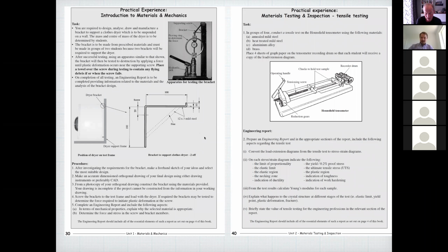It would hold together, and then I'd make sure that every student would go up there and with his fingernail feel the crack on the outside, and then I'd get them to try and feel if there's a crack on the inside. And there wouldn't be a crack on the inside because the PVB polymer between the two layers of glass has held it together. And then they've used that experience, and then you can explain crack propagation and how the polymer prevents the cracks from propagating through to the inside layer.